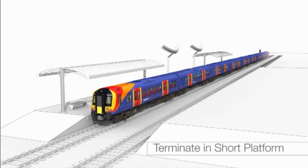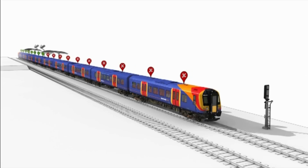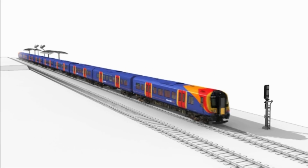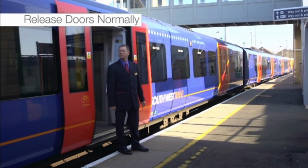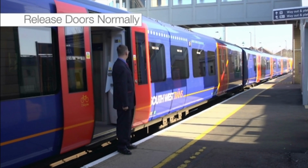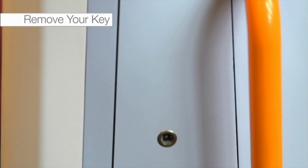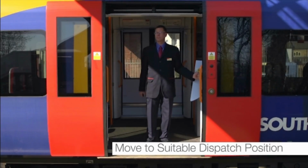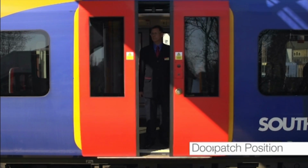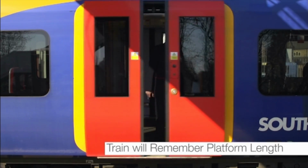If the train you are working terminates at a short platform and is required to restart in the opposite direction, as long as it isn't necessary for the train to draw forward clear of the starting signal, the following procedure should be followed. Release the doors normally, and as passengers are alighting, switch off the door panel you are working from and remove the key. You can then move to the most suitable location for dispatching the train. If you close the passenger doors, you will be able to reopen them, as the train will remember the length of the platform.